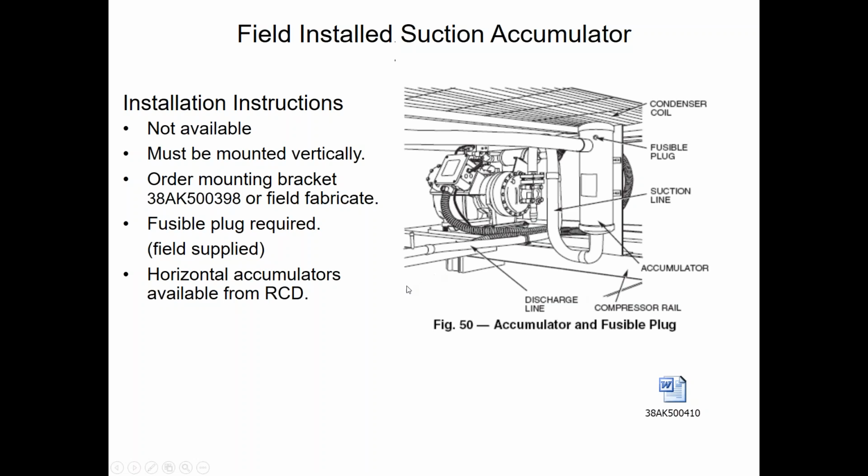But again, consult with us first before you install accumulators. Most of the time, you shouldn't need them, but there are some applications with VAV or VVT that we can put them on. Now, a lot of the units nowadays, if flood and start test didn't pass, come standard with accumulators. But again, get a hold of us.